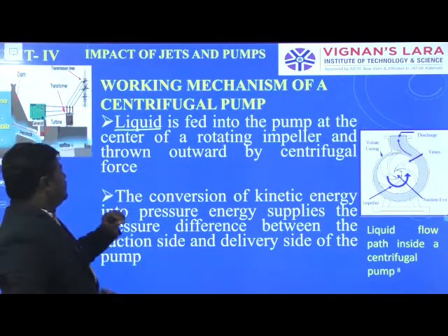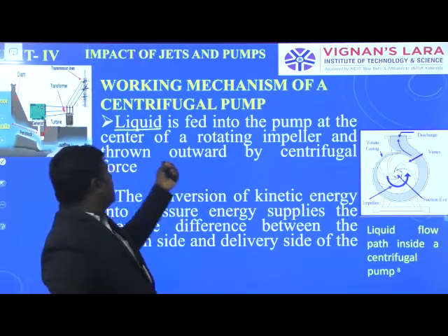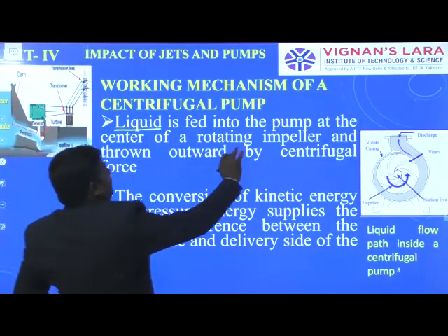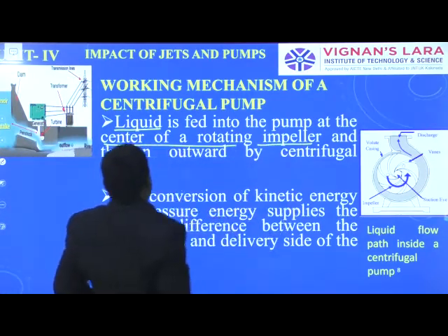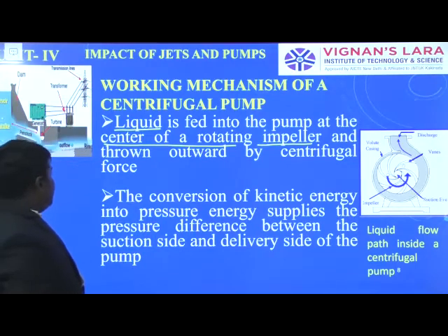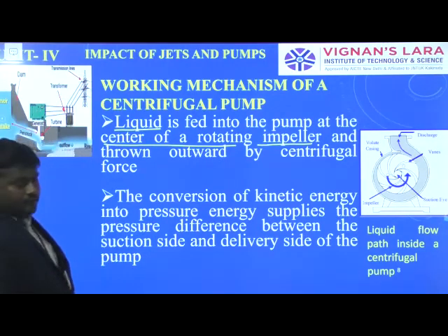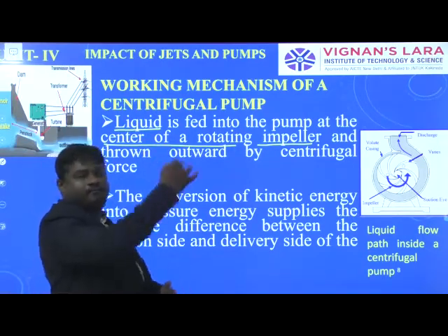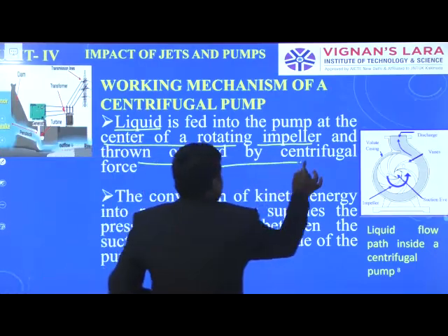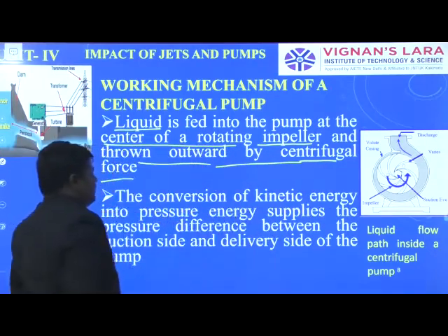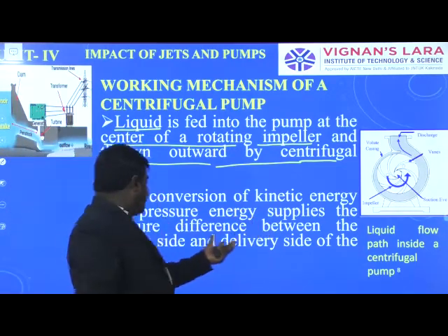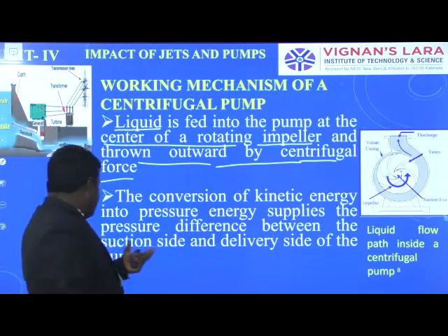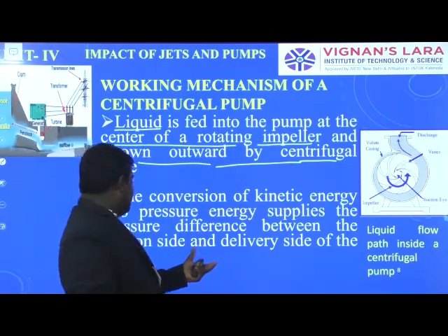The liquid is fed into the pump at the center of a rotating impeller and thrown outward by centrifugal force. The conversion of kinetic energy into pressure energy supplies the pressure difference between the suction side and delivery side of the pump.